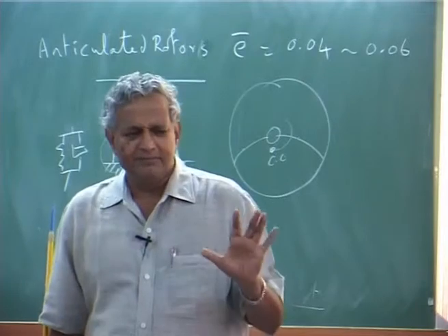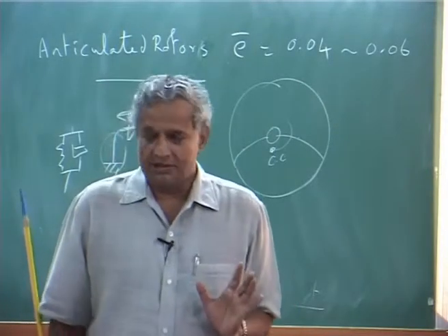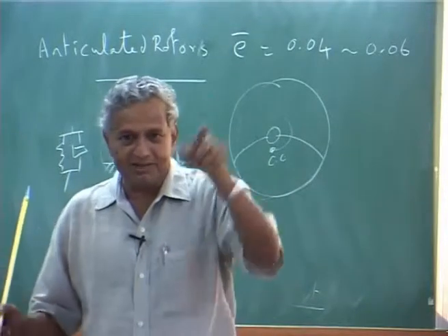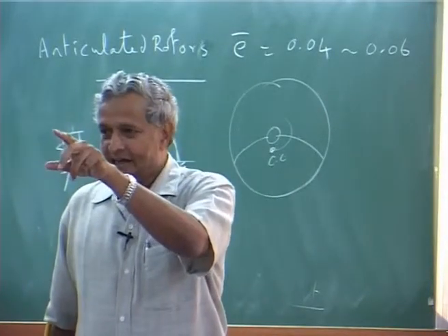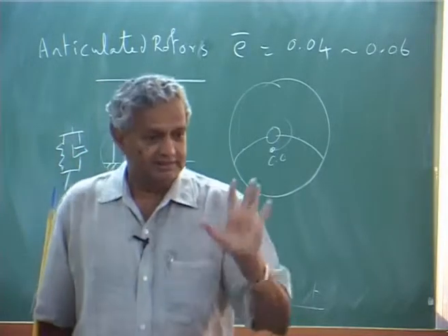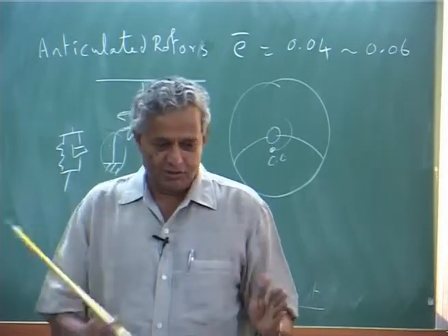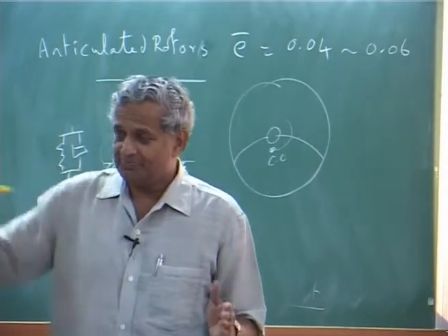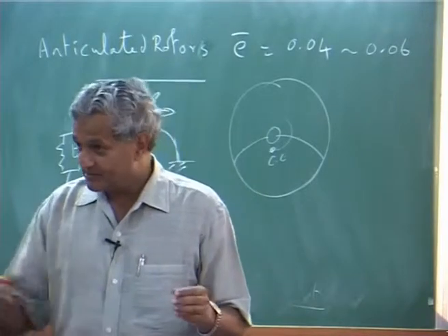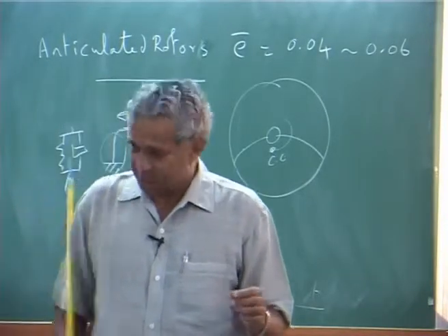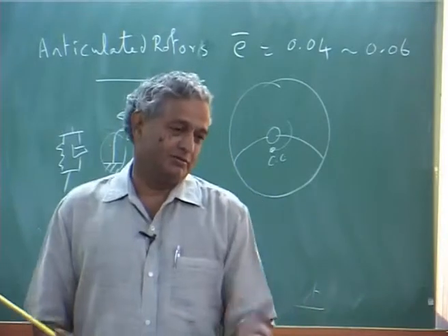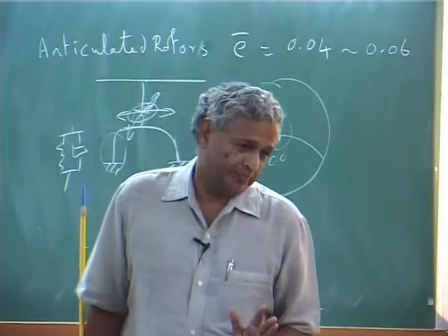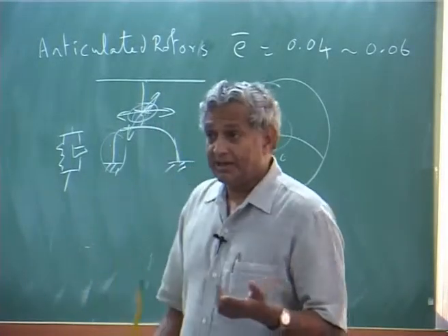In the fixed frame, the physics is okay, the CG is moving, that is all, but you have to know at what operating rotor RPM it really hits, and then you avoid that, okay. But your rotor RPM always starts from 0 to 100%, so definitely you may cross the resonance point, or if you want you shift it out. Best is you put a damper. Now there are two types of thing. One, you can put a damper right on the fuselage,